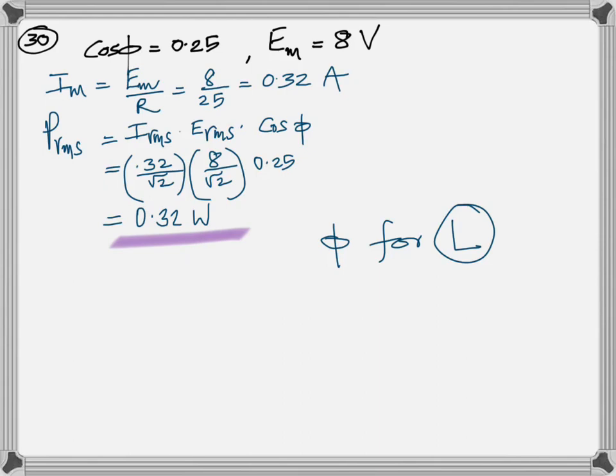One good example is a regulator for a ceiling fan, or those light dimmers, if you know what I'm talking about. Those are inductances, not a resistance. What you're doing when you turn it is changing the inductance. Now, what's the advantage of using an inductance there? In olden times, we would use a resistance there. I don't know whether you've seen the old box-type regulators for fans, which would get really heated up. That's a resistance, and that really is wastage of power.